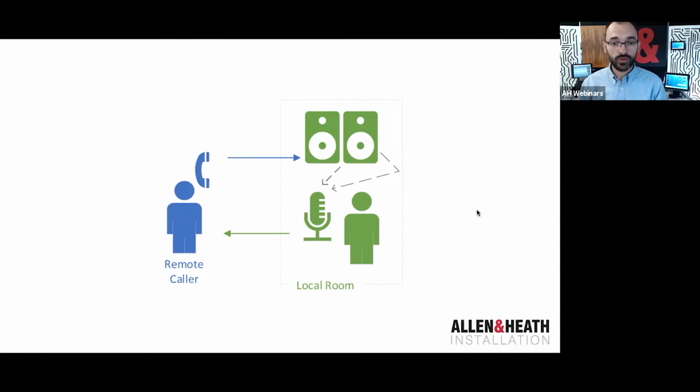Unfortunately, the response, particularly the impulse response of the room, changes over time, changes continuously. So every time you move around the room, you're changing the impulse response of the room. Every time you move a microphone, you're changing that response again. Even opening a laptop in between you and the microphone will change the pattern of the paths of the reflections and therefore the impulse response. So acoustic echo cancellers essentially need to constantly chase these responses. And they can vary in performance and implementation.